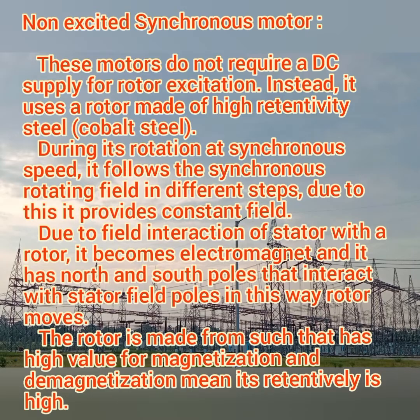In that, the first topic is the non-excited synchronous motor. This motor does not require any DC supply for rotor excitation. Instead, it uses a rotor made up of high retentivity steel, which means cobalt steel. During its rotation at synchronous speed, it allows the synchronous rotating field in different steps. Due to this, it provides a constant field in the rotor.